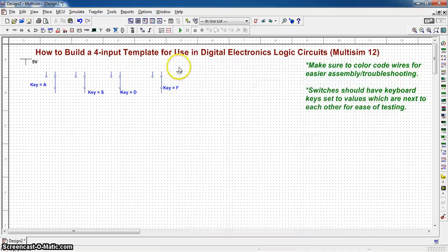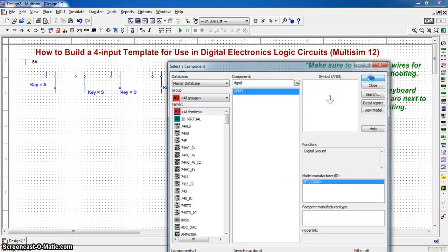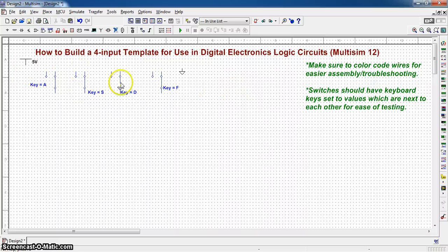Click OK there. Now, easiest way to do this is to start by connecting your VCC to the side closest on each of the switches. So I'm going to start here. So there's my first VCC wire. I'm going to do the same with the left connector on each of the switches to make it consistent. I'm also going to, in this case, leave my wires red because it makes it much easier to see VCC if it is simply just red.